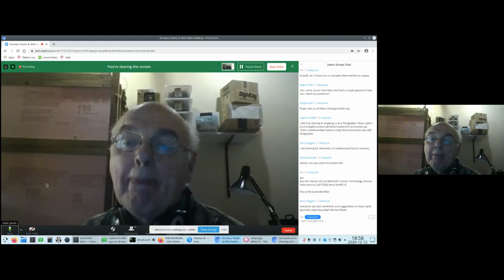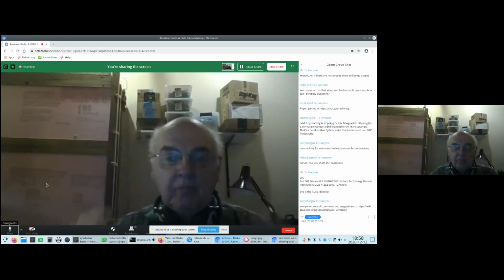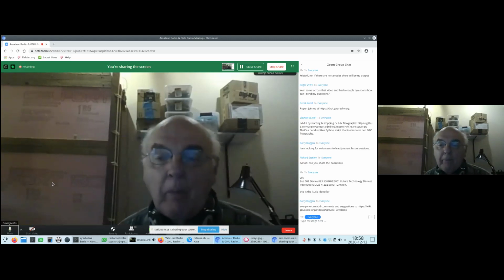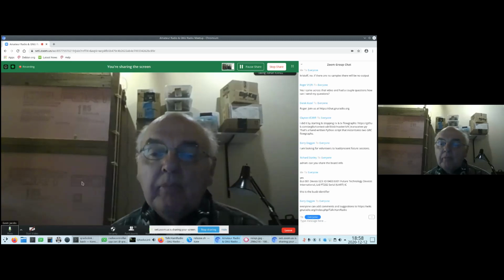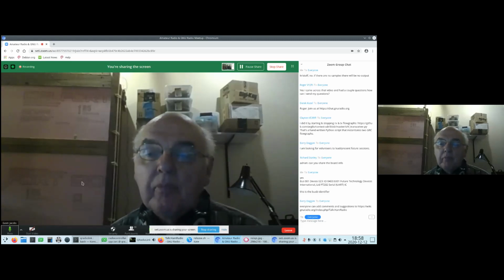And the other problem is using some sort of RF switch. There are RF switches on the market which are around 20 euros. Then you can combine them. I don't have any picture to show, but you can use multiple RF switches and make up some sort of path where you can use multiple filters and multiple amplifiers for various bands. Right now I have 4 bands configured, starting with 2 meters and ending on the 13 centimeter band using this method.